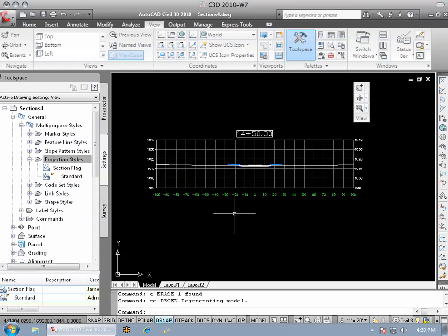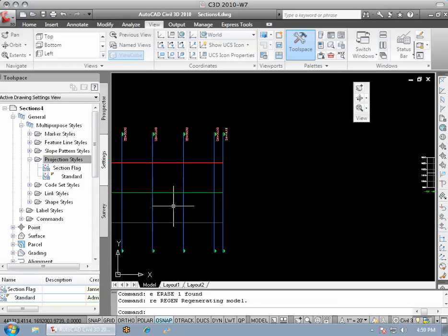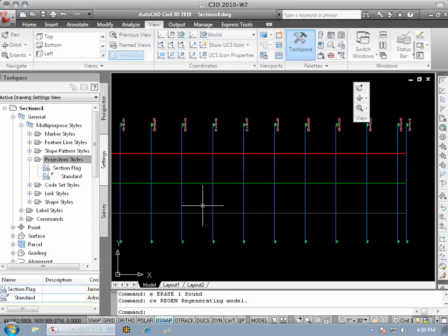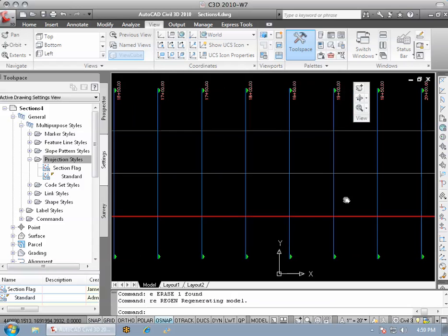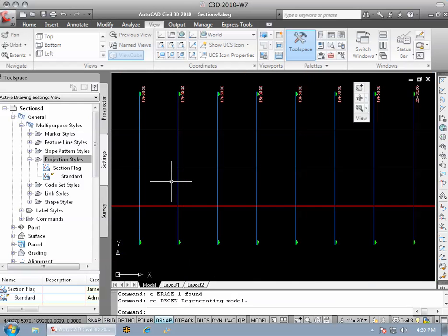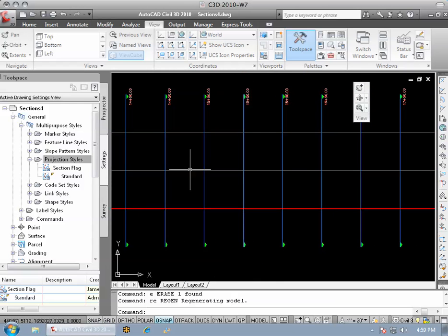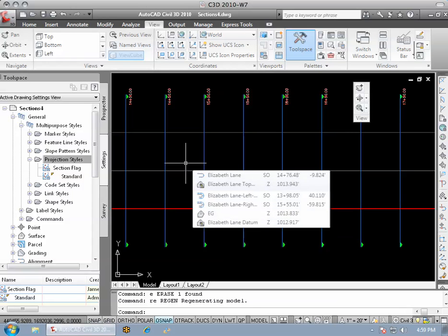And I'm just going to use a line to show it for a typical idea. Couple things we can do, but probably the easiest is to actually use the new object and projection option. And so what I'm going to do for the sections I've got is I'm simply going to find section 1450 here, and I'm going to draw a line to show it. And one of the things you'll want to do is actually use a 3D poly.